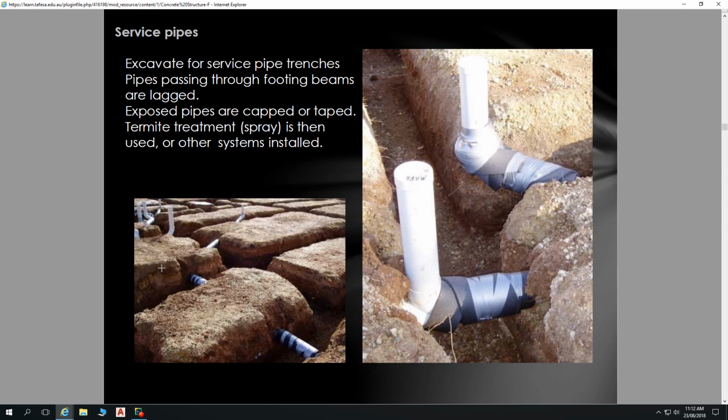Also, Eric was talking about slabs doing this before, and I mentioned, yes, that cracks pipes and whatever. That's what this spongy lagging is for. Well, it's the main reason. Take note of that. That is important because what we want to do is create a space between our pipes and our slabs, where we've got pipes going through a slab or through a beam like this.